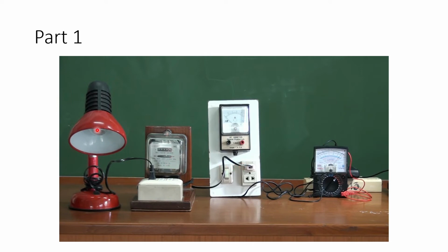You're going to be plugging in the light bulb with a determined wattage, and then you turn the whole thing on, and then you read how much power is being drained. In the meanwhile, you could also be doing the same calculation. As I mentioned earlier, you can count the number of rotations here to calculate the power if you know how much this thing rotates over time. So that's going to give you power in watts.